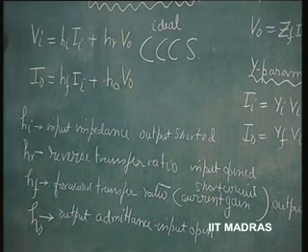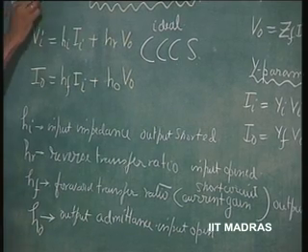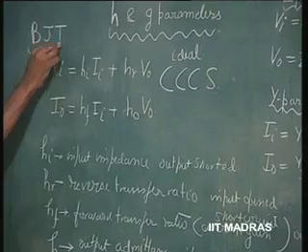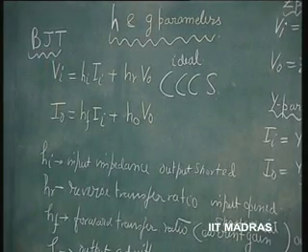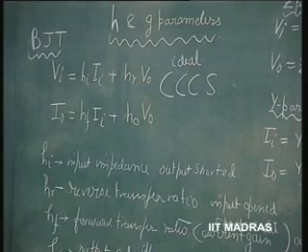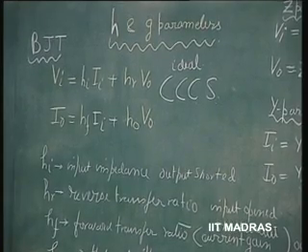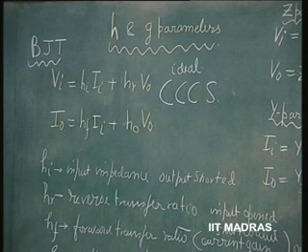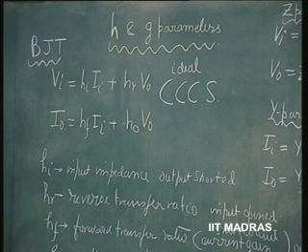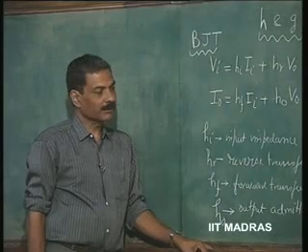Okay. A classic example of this category is bipolar junction transistor. I had mentioned about this earlier, right. This is very nearly equated to a current controlled current source, and H parameters are commonly adopted in defining the performance of a particular amplifier designed with BJTs.